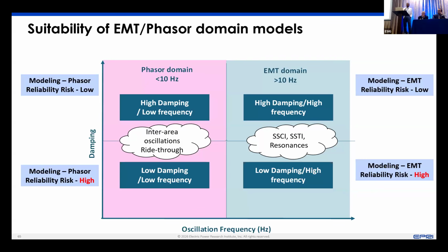If it's a blip, you want to make sure the blip doesn't push anything beyond maybe its basic insulation level and stuff like that. But if all of those things are there, you can deprioritize it. What you want to really understand are these events that are growing in nature, that are not damped out by any kind of system damping that's available.